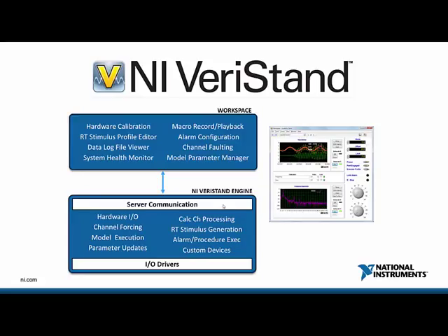So if you wanted to run batch tests overnight, for instance, you'd be able to take your PC home with you, and the VeriStand engine could run all of your tests, and then when you came back, you'd be able to plug that back in and see the results of all your data. So it's a very, very useful and nice way to do the HMI or user interface to real-time engine configuration.